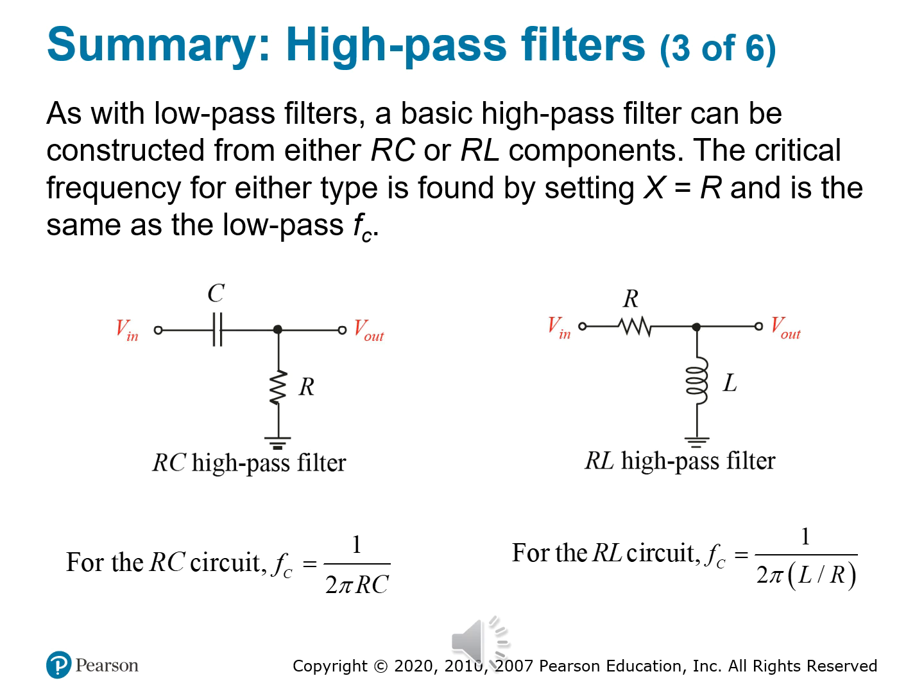So with the RC high pass filter, in the design of the circuit, the capacitor comes first, the resistor comes second. And what about low frequencies? Well, they're blocked by the capacitor. And what about high frequencies? Well, they flow through just like a cool summer breeze.